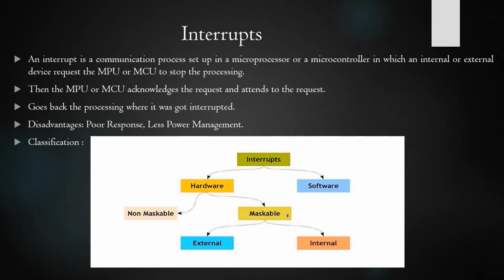Then interrupts. Next we'll see interrupts. Interrupts is a communication process set up in a microprocessor or a microcontroller in which an internal or external device requests the MPU or MCU to stop the processing. Then the MPU or MCU acknowledges the request and attends to the request.